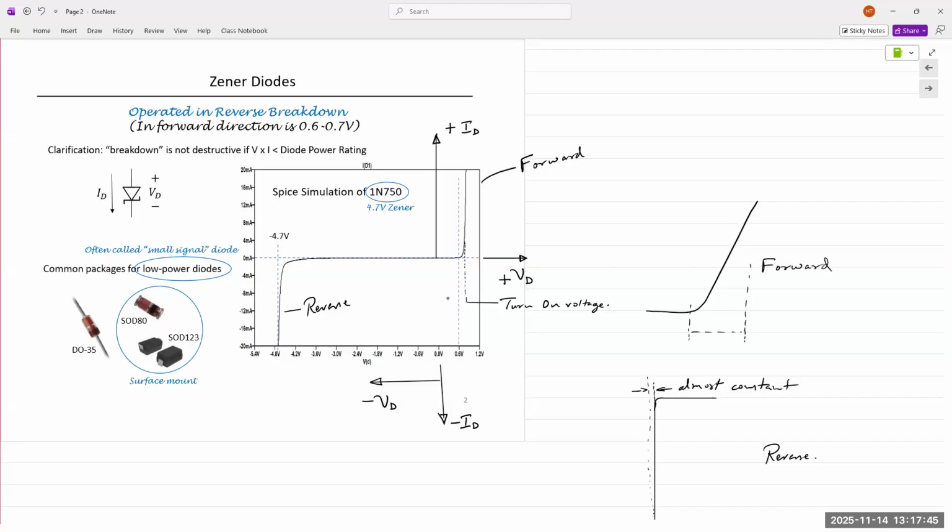And when the junction breaks down, that's when a large amount of carriers flow through, meaning a large amount of current is now flowing through the diode, but it's in the opposite direction. We are applying the reverse voltage, and so current flows in that reverse direction. And that point is known as the reverse breakdown voltage. For typical diodes, that reverse breakdown voltage is tens of volts. A regular silicon diode that we use, it's up to 50 volts.